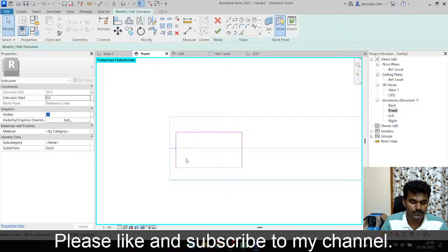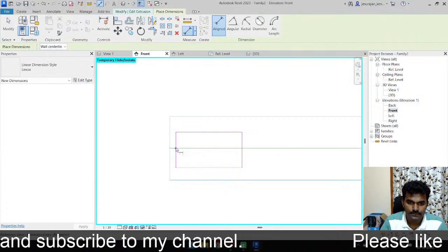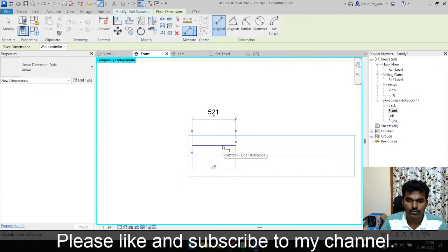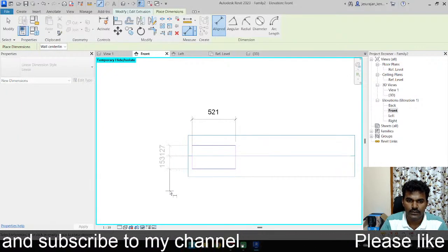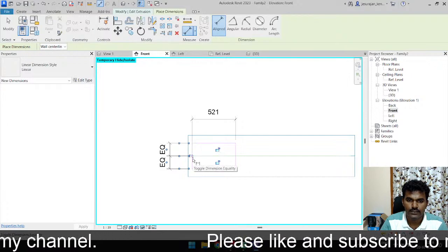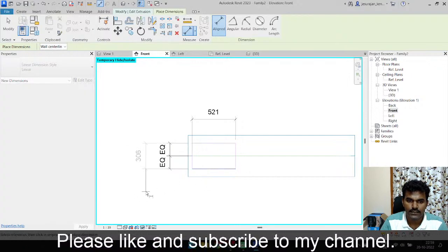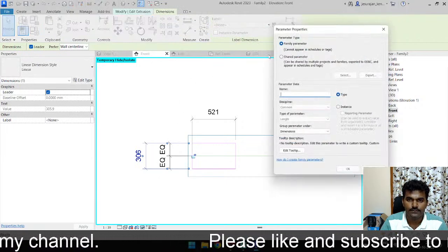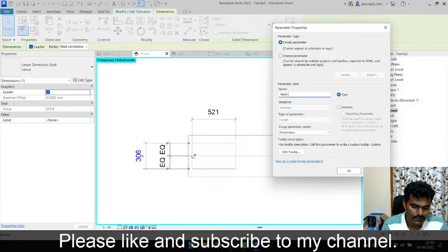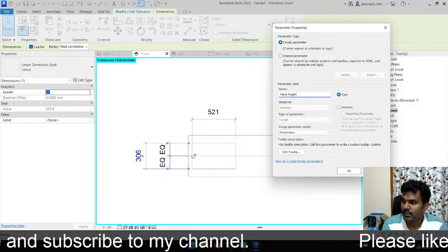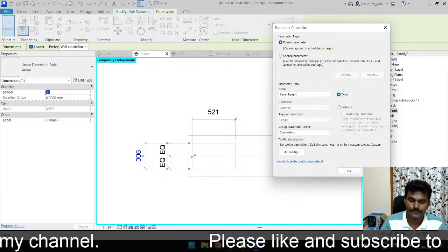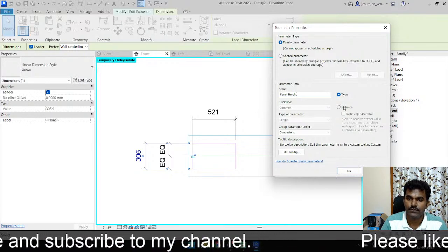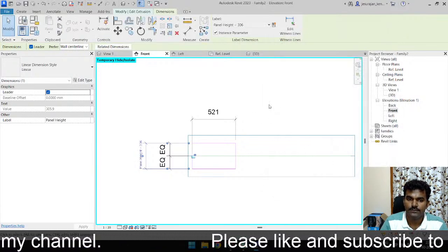Yes, it's a success. And again, select the point and select the line. That's a good move. Keep this as equal. Okay, and create a dimension. So this is going to be panel height. Panel height. Keep it as instance and okay.